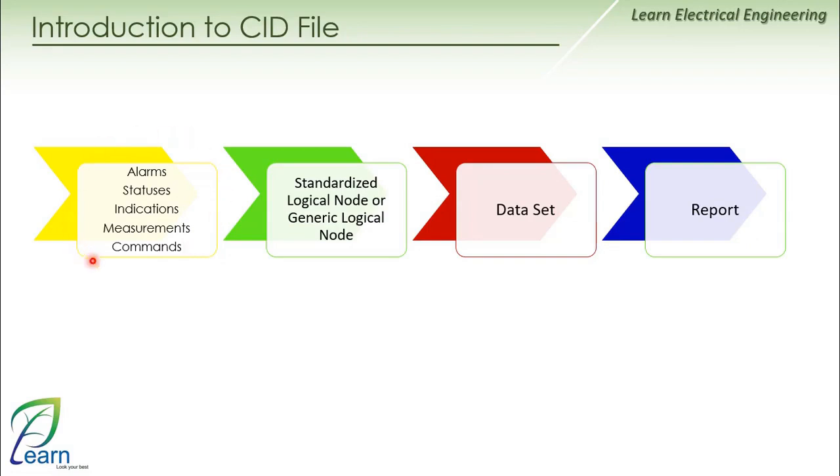Are these communications sent from the relay to the SAS or received from the SAS to the relay? No, there are also other things. What are the other things? You might have something like the virtual signal or the software signal that comes out of the protection functions, such as tripping or pickup, depending on the communications you need to program. It can also be logic.